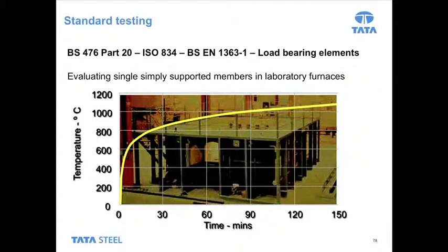So that curve tells us a couple of things. First of all, it tells us that in a standard fire test, the product being tested will be deemed to fail at either 30, 60, 90 or 120 minutes, depending on how far it goes along that curve. And that's when it's heated using this time temperature profile.